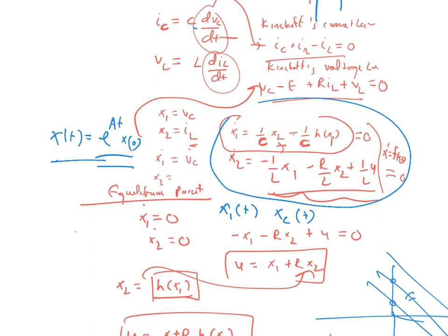Here, no. So you basically approximate. You can draw some pictures, phase plots, for any nonlinear system, which gives you a kind of behavior of how these systems will behave. That's a very powerful tool to analyze at least the initial part of the system, at least for second order nonlinear systems.